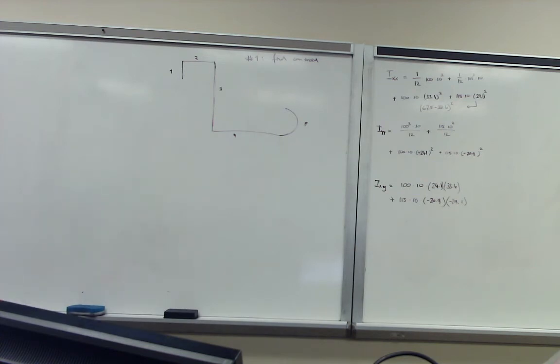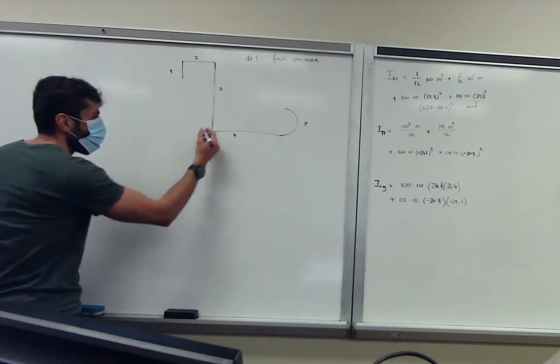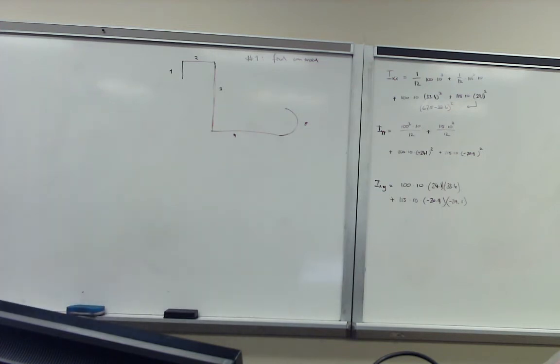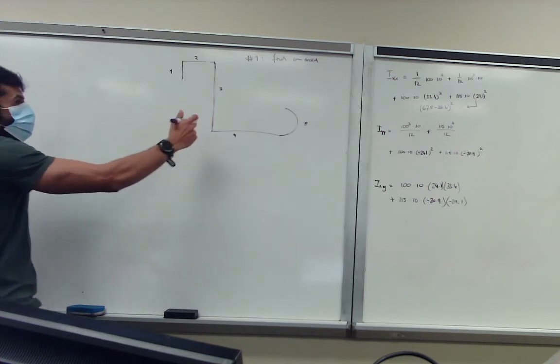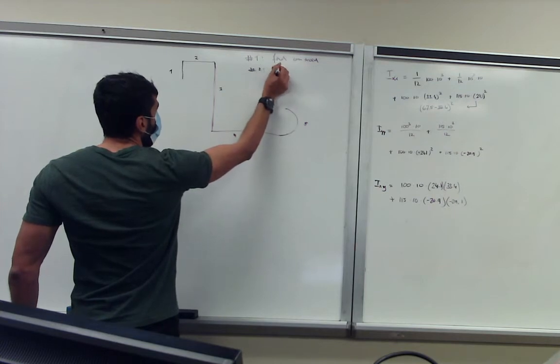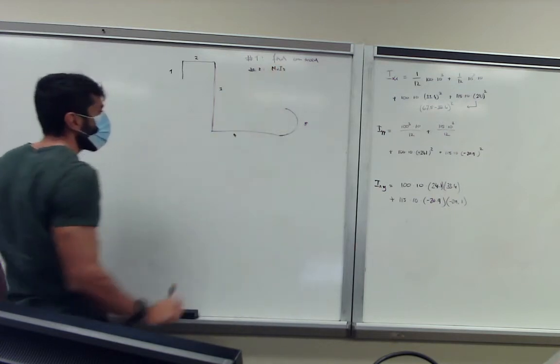And often it's just choose a point that's simple. It can be a corner or something that you know. In this case, I would choose this one. So in this case, you would still use 1/12 b h cubed. Now you've come to step 2, and that's the moment of inertia. So deriving moment of inertia.